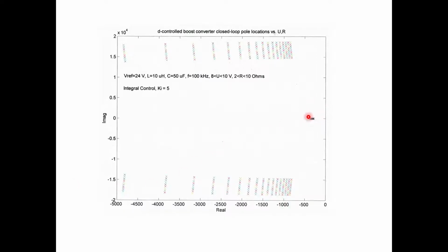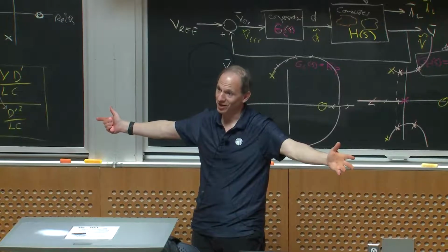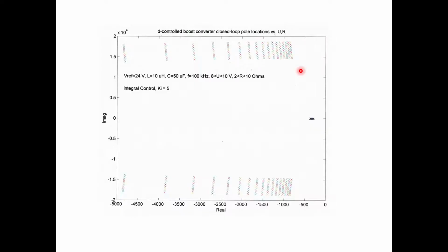But that doesn't mean there's not some small oscillations. The small oscillations aren't going to make your circuit blow up, and that's why they say, oh, it's great, it's very, very stable. And it's true. The problem is, if these are wiggling around, even if it's very, very small, that might be unacceptable as a response at the output. That's the point I wanted to make.